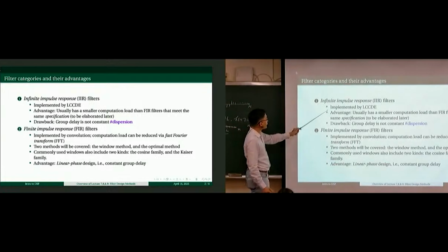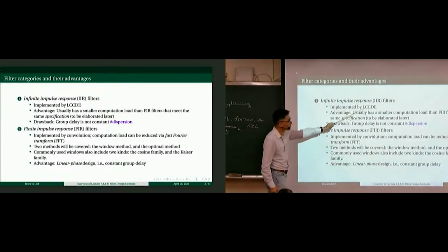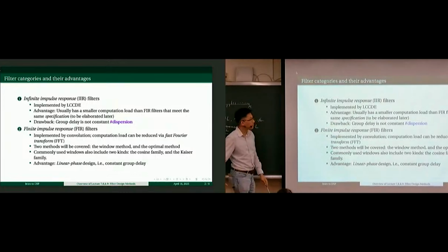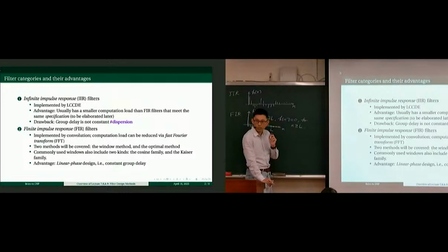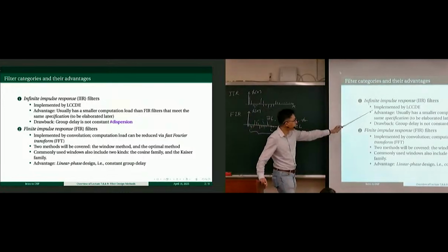IIR filters are always implemented by linear constant coefficient difference equations, things like y of n on the left and a linear combination on the right. I could not emphasize this enough: IIR filters are always implemented by LCCDE. That's an important concept.